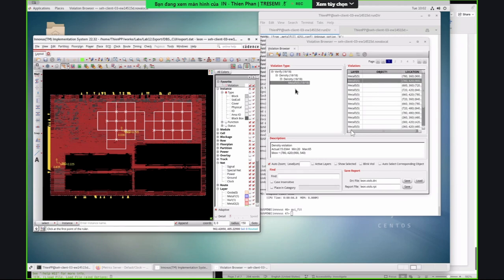Metal fill emulation, where it's aware of what the metal fill is going to look like. So during the optimization in Innovus, it could consider that and predict. So it will help with minimizing the iteration. That means minimizing the surprises after metal fills are in, right? In terms of timing closure.